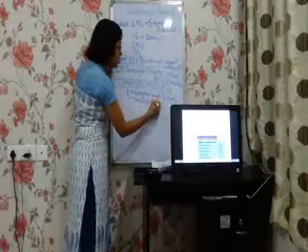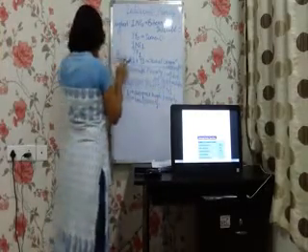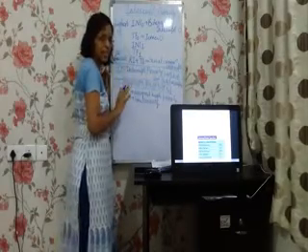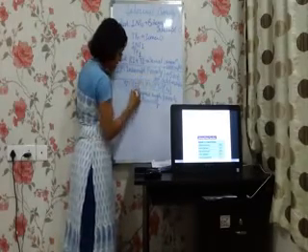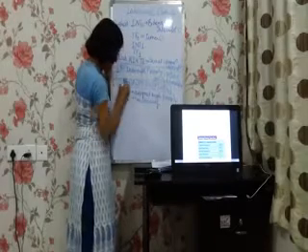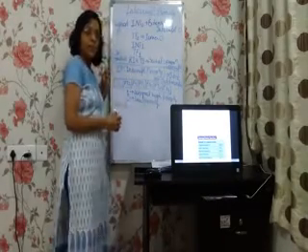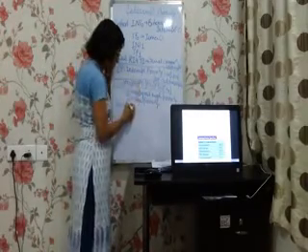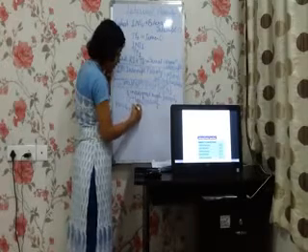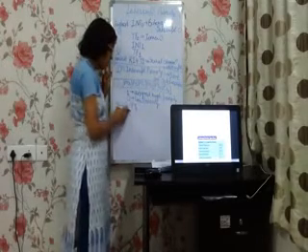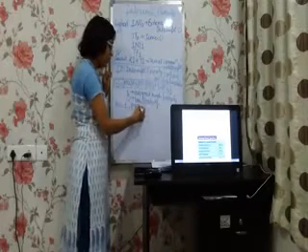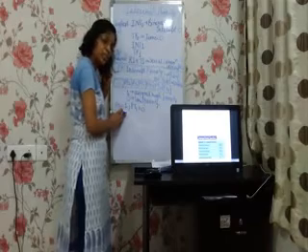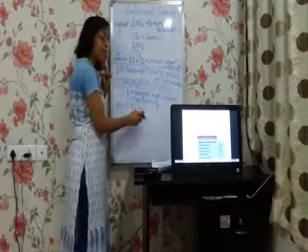Though we know that RI plus TI, that is the serial communication interrupt, for example, is given the lowest priority, if the PS bit in the IP register is made 1, and suppose there is a signal coming from timer 1 also, but because we have made the PS bit 1 and PT1 0, the serial communication interrupt will be given a higher priority as compared to the timer 1 interrupt.